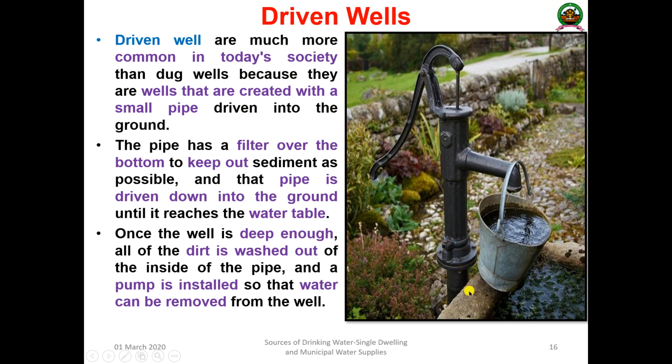This pipe reaches directly to the underground, and the water will be taken from there. The pipe has a filter over the bottom to keep out as much sediment as possible, and is driven down into the ground until it reaches the water table. So this pipe will enter deeply into the water table, and the water will be collected from there.